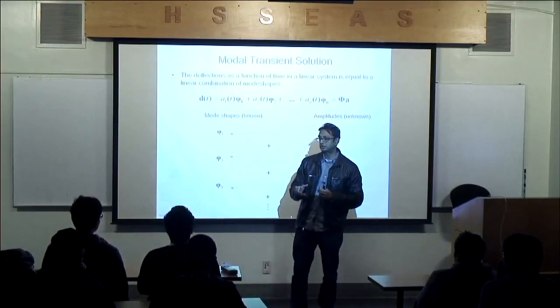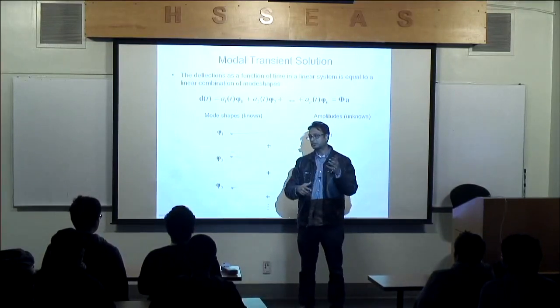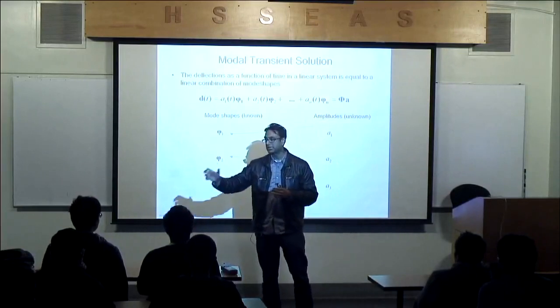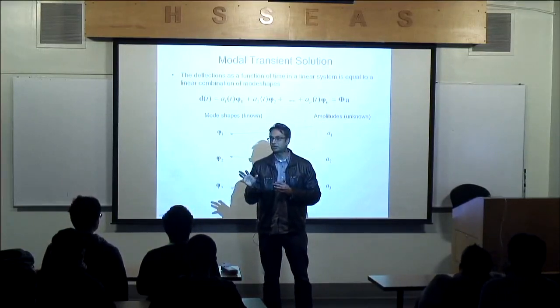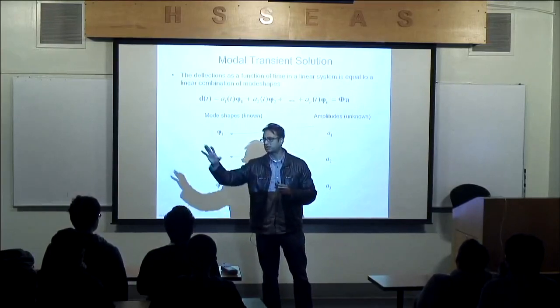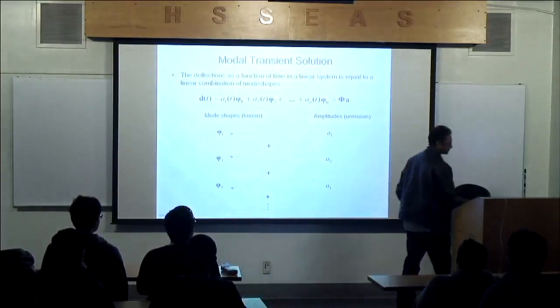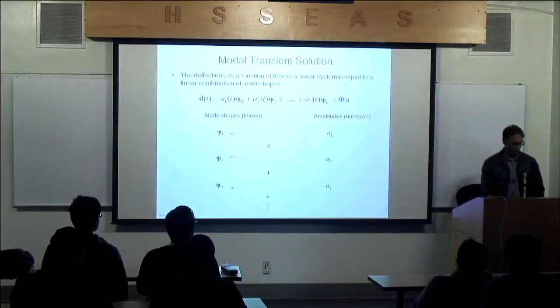So now instead of solving a 1 million by 1 million stiffness and mass matrix and inverting that and using the Newmark beta method at every time increment, I've simplified the problem into solving it for fewer degrees of freedom. By way fewer. I mean, a huge decrease in their number. Is that clear? Is that clear? Yes, that verbal description is clear.